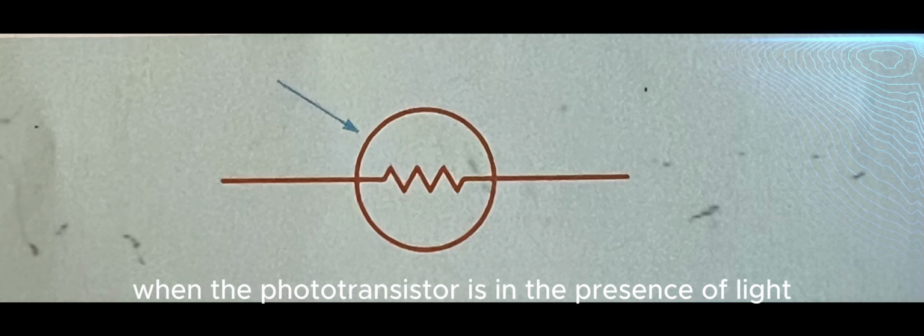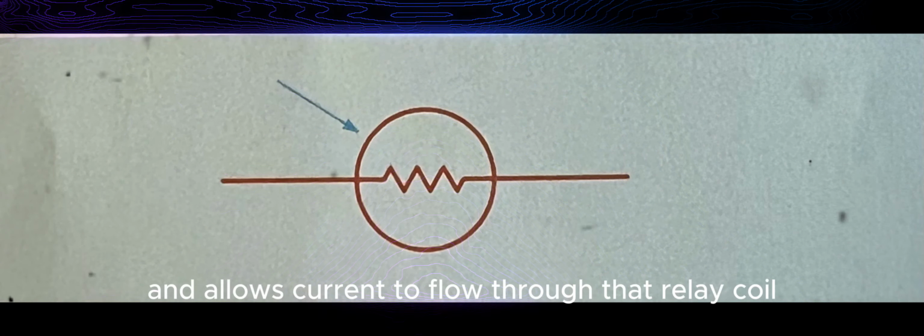When the phototransistor is in the presence of light, it turns on and allows current to flow through the relay coil. The diode connected in parallel to the relay coil is known as the kickback or freewheeling diode. Its main function is to prevent induced voltage spikes from occurring when the current suddenly stops flowing through the coil and the magnetic field collapses.